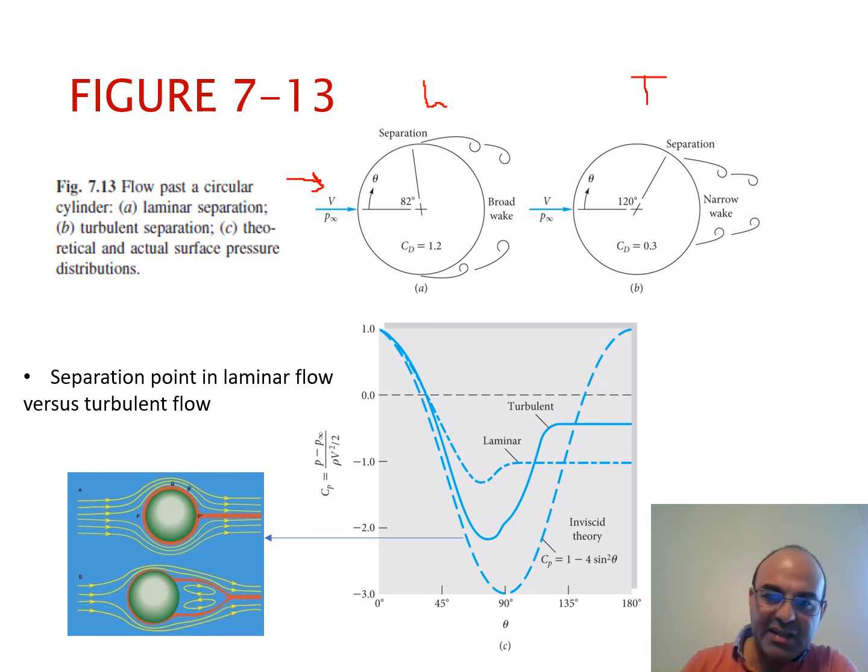So on this point, the flow will come to a complete stop. This is called a stagnation point. The velocity will be converted to pressure as it approaches this point. The kinetic energy is converted to pressure energy.